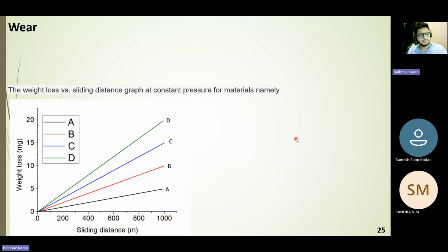ASTM determines these, as you have heard about ASTM standards, right? There is a standard book for all. Because the tests I conduct and the tests someone else conducts somewhere else should be at the same level. We have to match our results. And how can we match our results? We have to keep the base or the parameters similar so that we can compare our results. Like, okay, this material has a higher wear rate than my material, so we can compare that. That is given by G99.